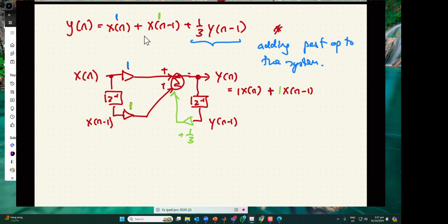Now the equation says plus 1/3. So it's sitting there, plus 1/3 y[n-1]. And then that's it. That's the equation we have, and we now know how to draw the block diagram. So there are 2 marks in the exams, guys. If we ever ask you to draw DF1, this is called the direct form 1, and it comes from the difference equation directly.